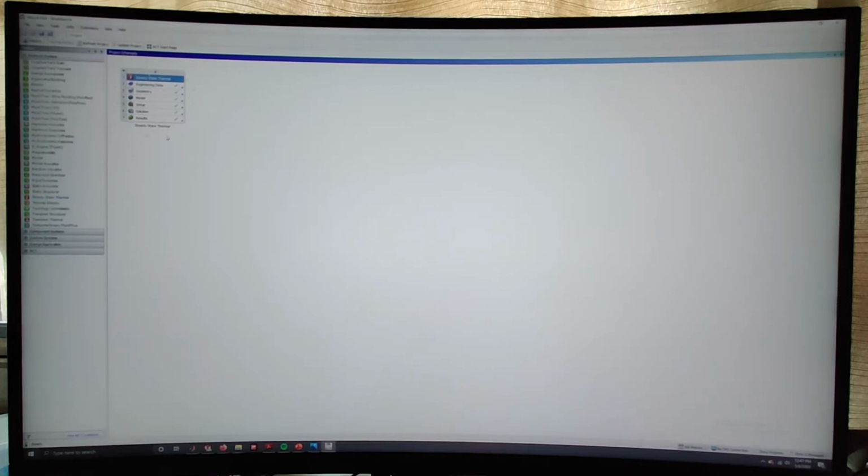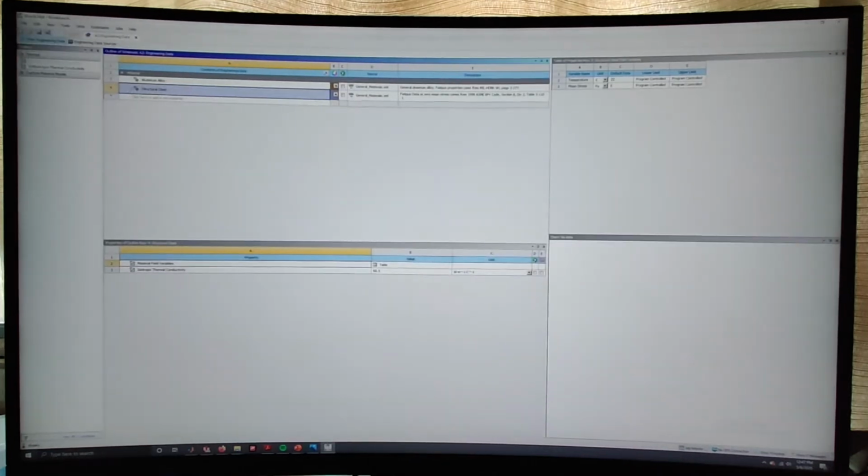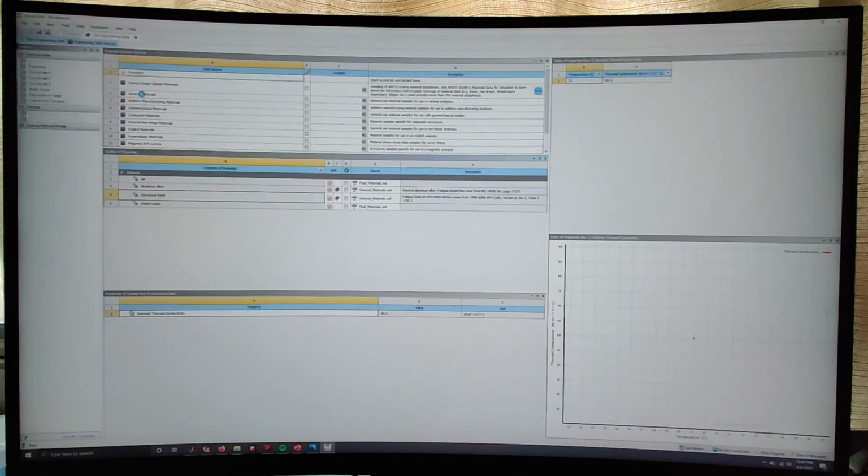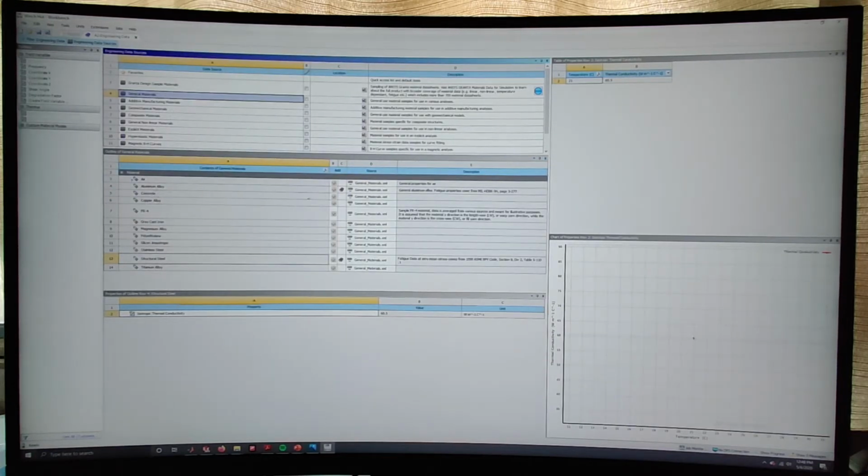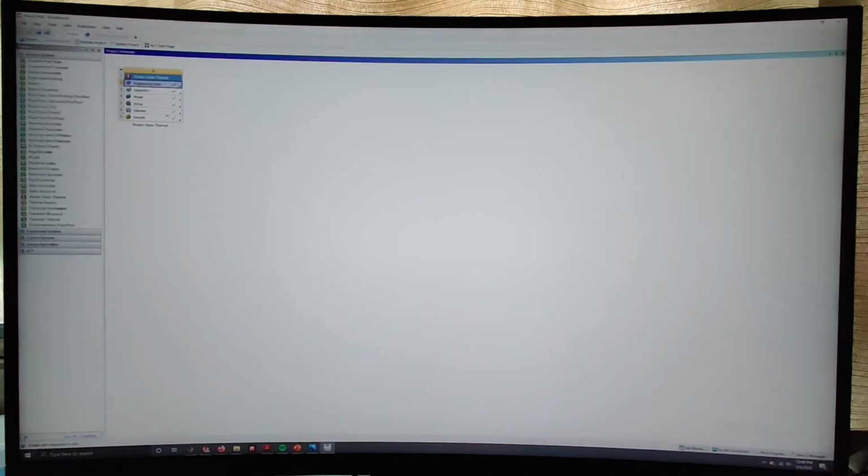So that's this guy. If I click on Engineering Data, I can run in here. It'll auto-populate with structural steel, but most of these parts are aluminum, so you can run over here, General Materials, here's aluminum, and then you can add it to your workspace here, or whatever other material you need to use. So if we jump back here, then we want our geometry. Here, I've already imported this, otherwise it says import geometry, so now they want me to replace it. And then you can browse for it, or it recognizes that I've already uploaded this winch step file.